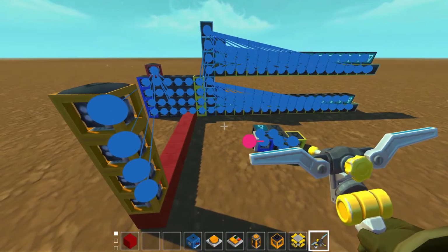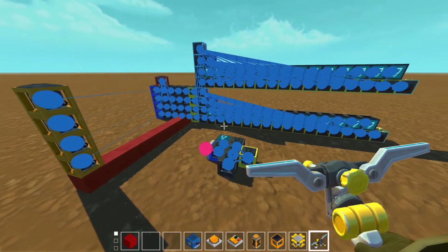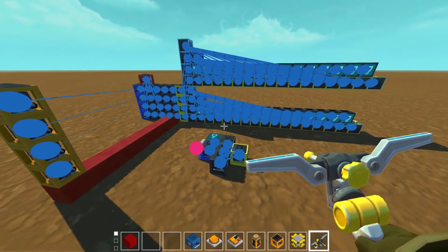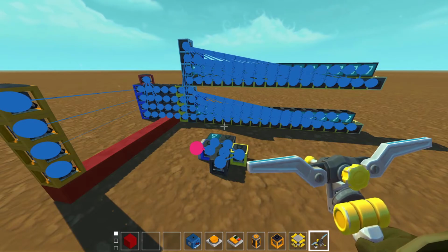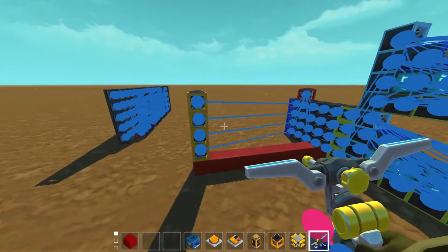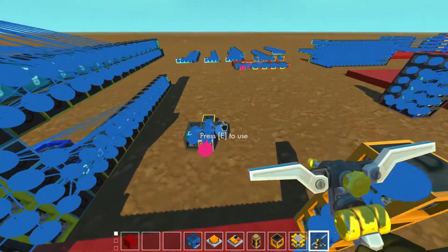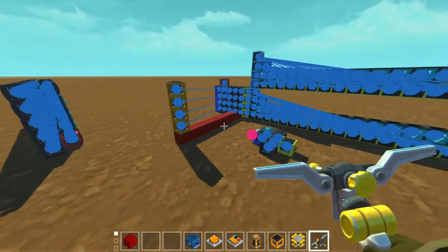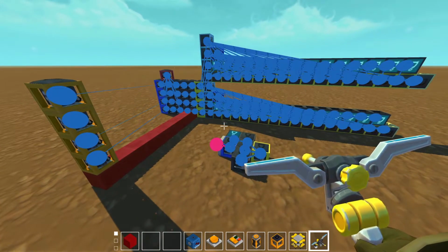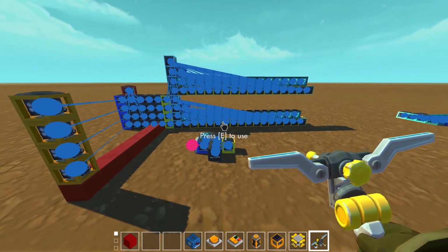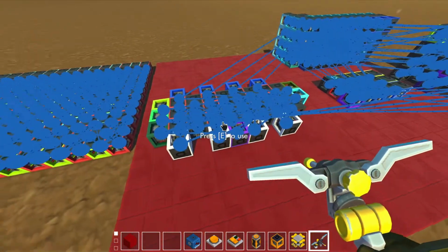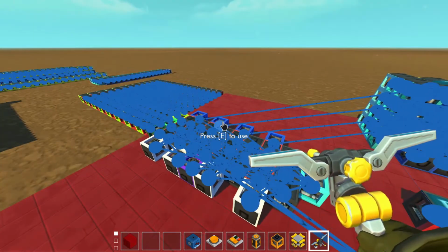Yeah, and so it can have a special case in which if we are in state 3 and it detects a value greater than 5 in the accumulator, then it will branch to state 11, in which case it will add that value in the accumulator to itself to double it. Which, a funny detail is, doubling a number is easy, you just need to bit shift it.